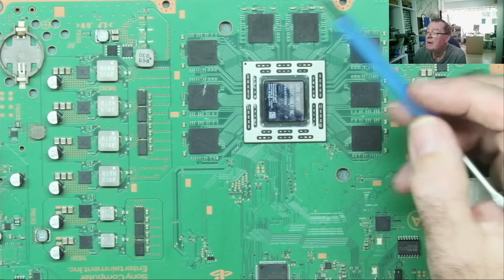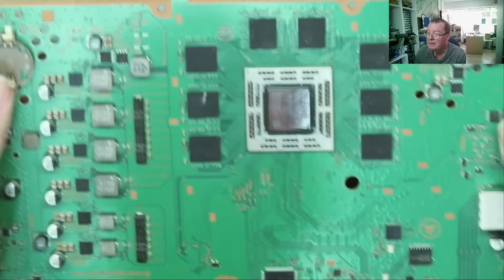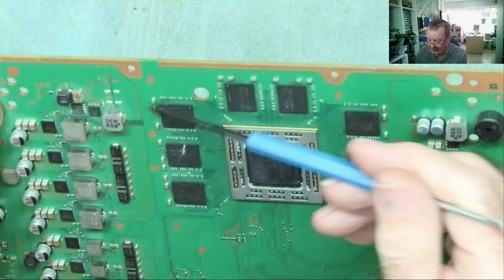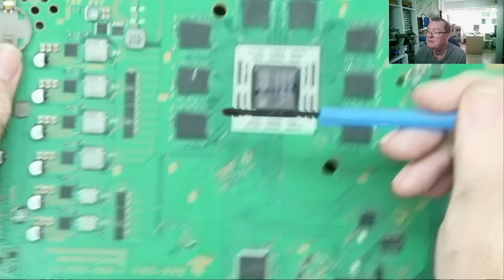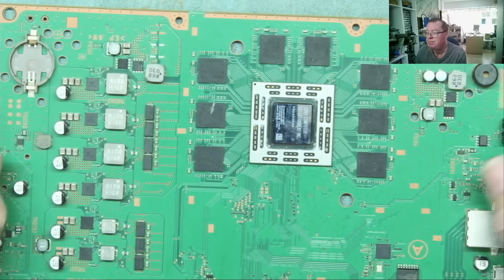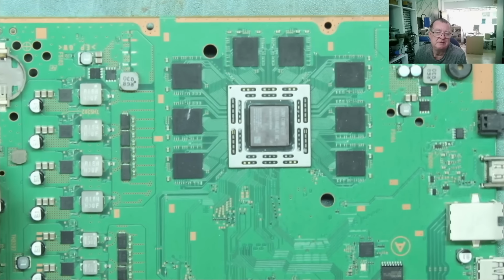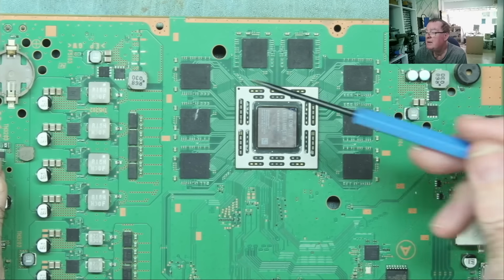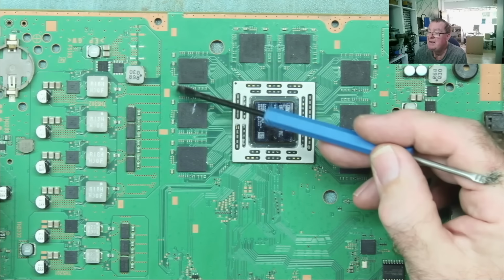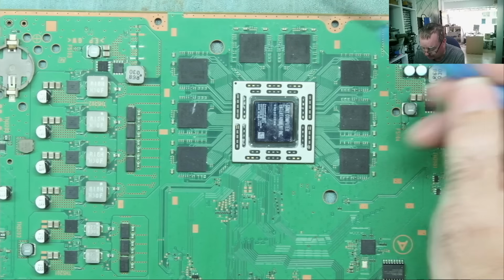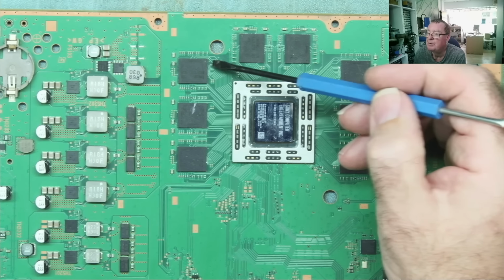Yeah, and the technique to use, you have to get flux underneath here, which you can actually do because there is a very small gap. We just put flux here, we get a hot air gun, let it all run underneath. And then again, you need a preheater to heat the board up to somewhere 150, 180 degrees, somewhere in that region maybe. And then use hot air or again a rework station to heat from the top, melt the solder, and to reflow it, really then you should very gently tap on the chip.